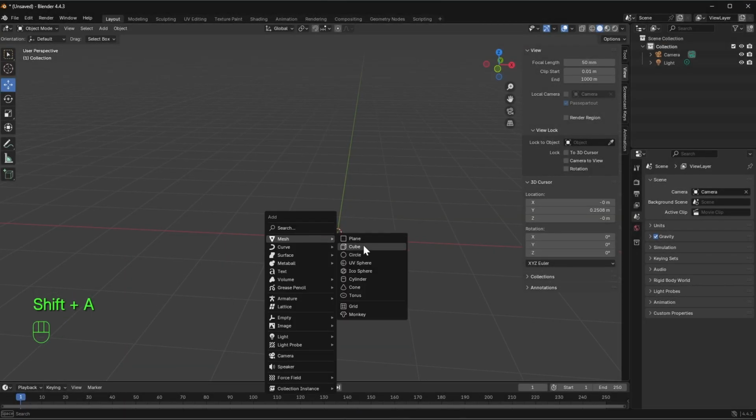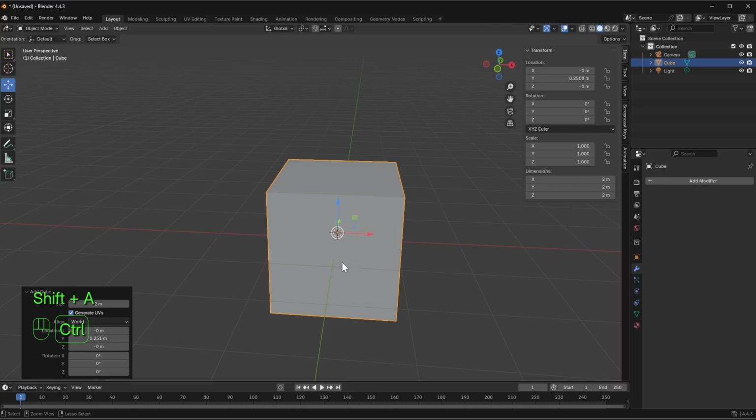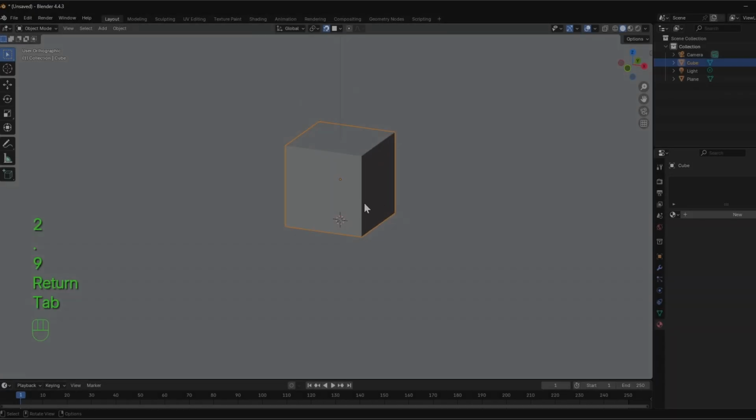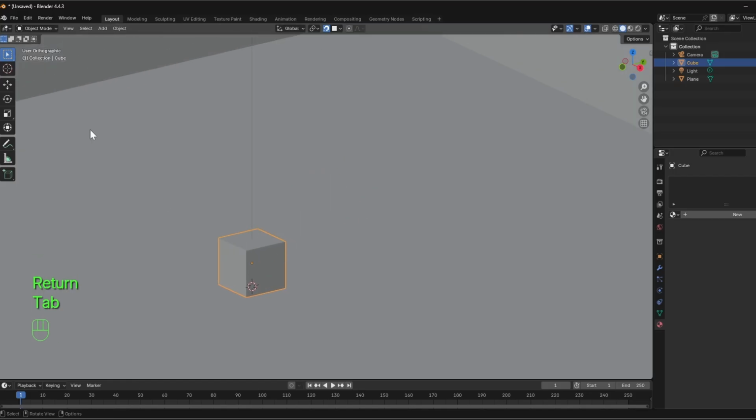But I'll show you how to do that here. Hit the N tab, select item, and then there's mean crease. And now you have a creased cube, and that's the simplest way to do it if you're just doing it in Blender. It also can be more effective and efficient if you just add edge loops.